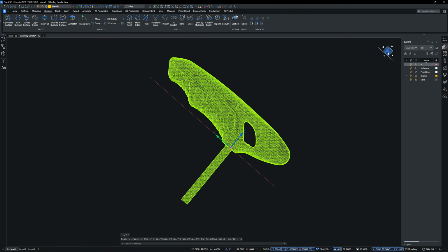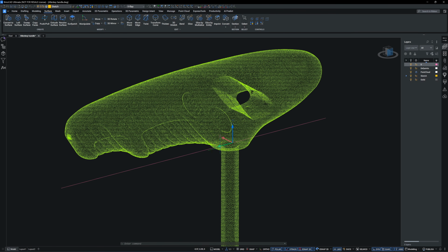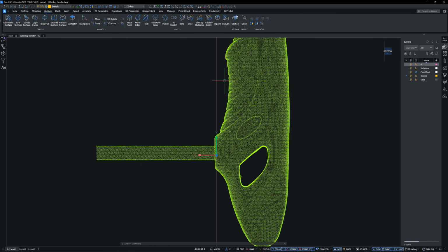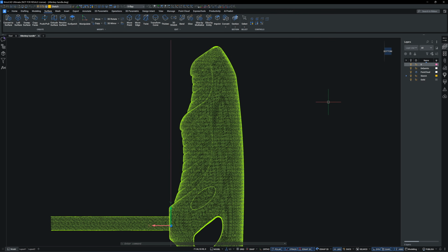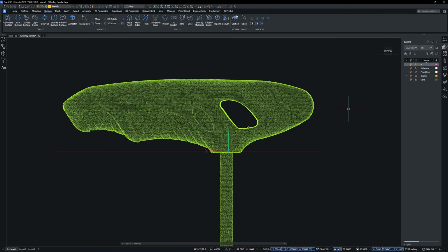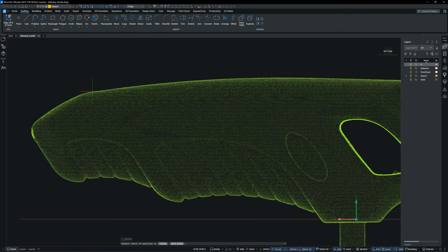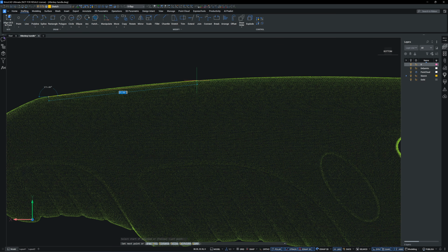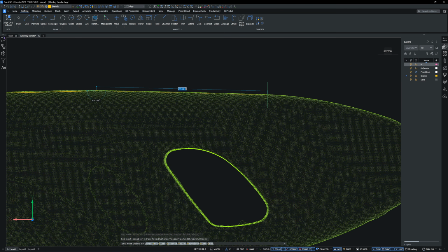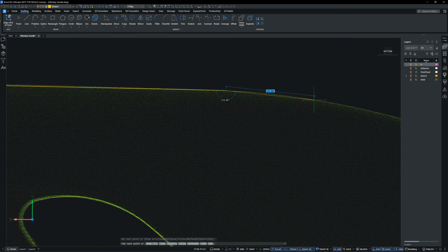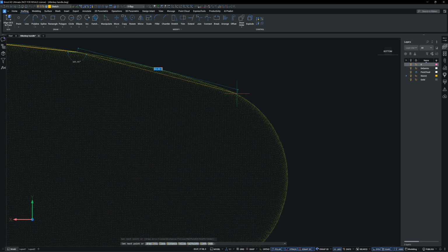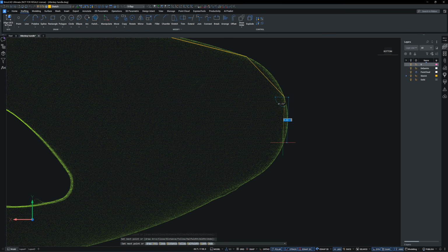I can tell this model must have been created with a polygonal modeling tool. Back in the World UCS, I will create the first sketch on the mirror plane. But before that, I need to rotate the UCS y-axis by 90 degrees so the XY plane lines up with the sketch plane. If I model this handle using solid commands, the process would be faster, but the geometry wouldn't perfectly match the original. For sculpture-like models, the best approach is surface modeling. It takes longer, but it captures the shape more accurately.